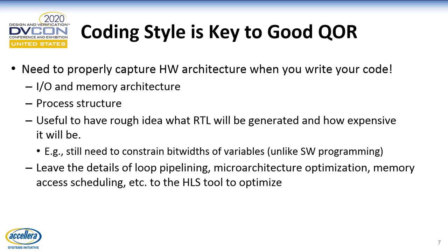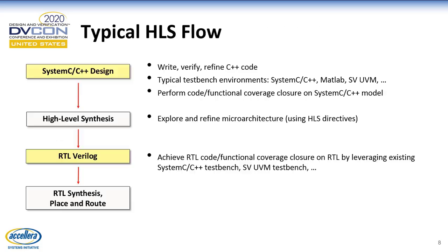So there's a lot of details, for example, the register sharing, the construction of the overall control of a particular block that you can leave to the tool, and it can take care of details like loop pipelining and so forth, memory access scheduling and so forth. So this is an example of a typical HLS flow where the user codes in SystemC or C++